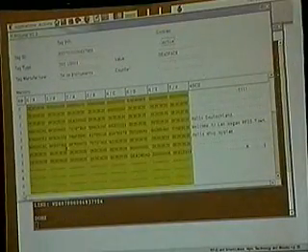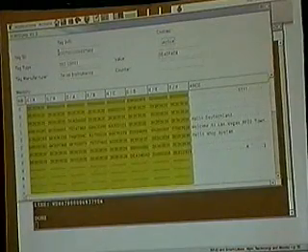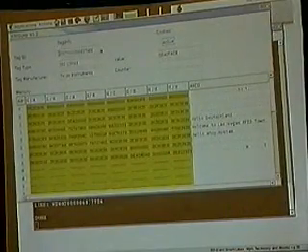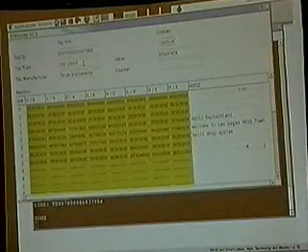And don't steal it. The next myth is that RFID chips can be read from a huge distance. This is absolutely not true. You must be directly in this powered field to read the chip via the antenna. We have made some tests at our lab and we found the maximum distance with a huge gate. I'm going to demonstrate and show the picture of one of these gates: 10 meters. After 10 meters, it's gone.